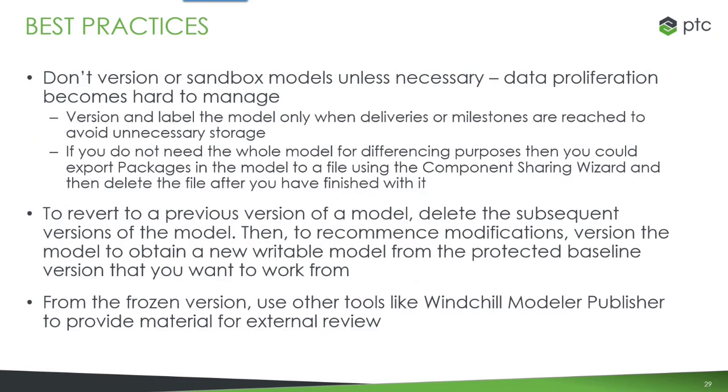Try to avoid creating unnecessary versions or unnecessary sandboxes. It can be easy to result in a situation where you have hundreds of versions and hundreds of sandboxes of a model. You kind of lose track of the overall design evolution. So try and avoid that, only create them when necessary. Version and label models and packages when deliveries or milestones are reached. So don't do it all the time.